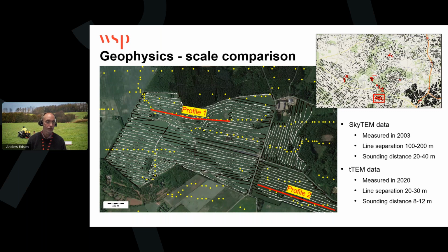You can see the position on the map to the right. One thing that should also be mentioned here is that all the black tracks show what data was measured with the TTEM method, but during processing, noisy data and other data distorted by sources other than the subsurface were removed from the data set, and that's why the data set available for interpretation is the white dots indicated in this map. You see this linear structure passing through the area here is actually a power line, and that's why the data cannot be used here.